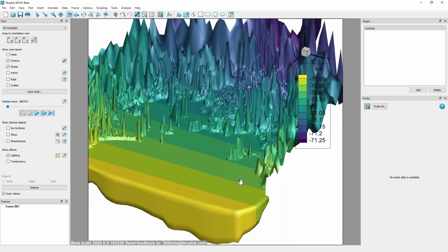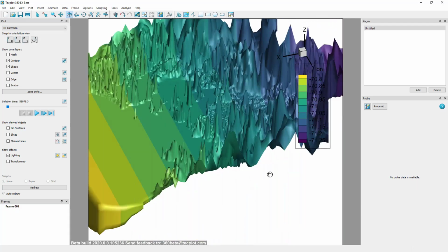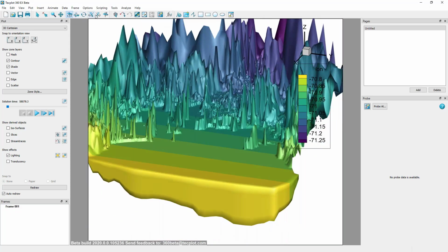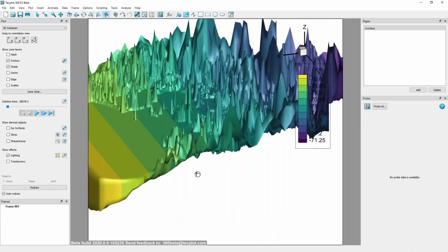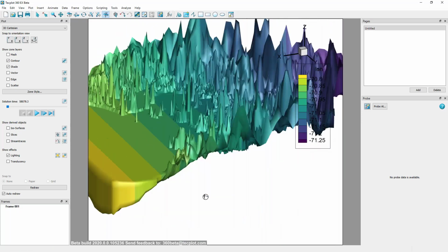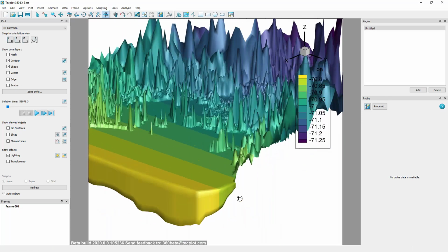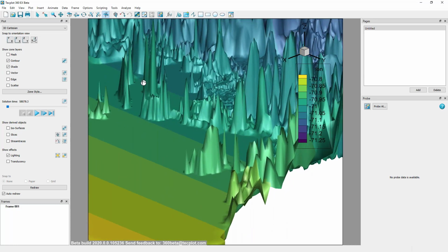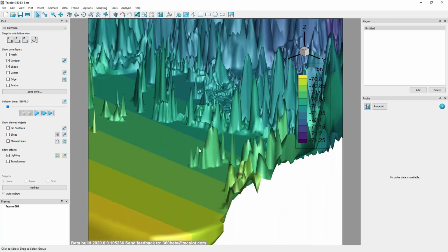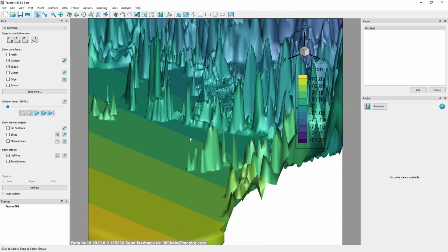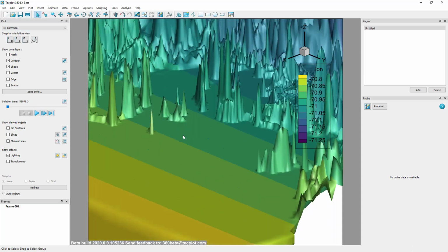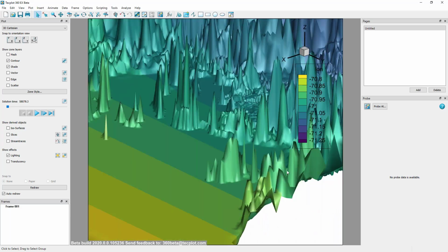And then we have a whole host of rotation tools. So we have the standard rotation, rollerball, twist, and then these XYZ axes locked rotations, which can be useful if we want to maintain a certain orientation in our plot. So if I zoom in a little bit, I can click and hold the middle mouse button rather than having to use the magnifier tool. I can click and hold right click to translate, and I can control right click to rotate.